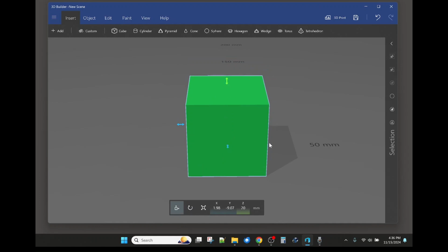The next tool over is Rotate. Select it and the toolbar changes to the rotate parameters, named roll, pitch, and yaw. This convention is from the airplane world, but it suffices to recognize that roll corresponds to rotate around the x-axis, pitch corresponds to rotate around the y-axis, and yaw corresponds to rotate around the z-axis. Note that the center of rotation is the center of the object wherever it is, not the actual intersection of the x, y, and z scene axes.